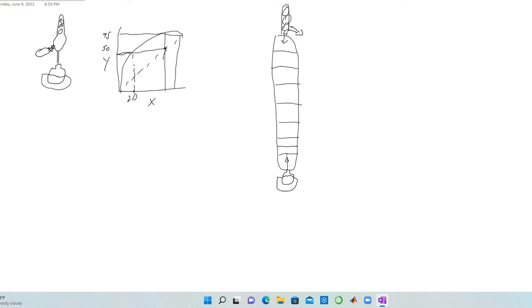So as this liquid is going to travel down the column, while the vapor is traveling up the column, we're going to have condensations on each of these trays. Each of these trays is going to be a single staged flash like what we just talked about over here. And we're just going to be doing it multiple times in a row without the need of condensation because we have reflux to pull energy out of the system.